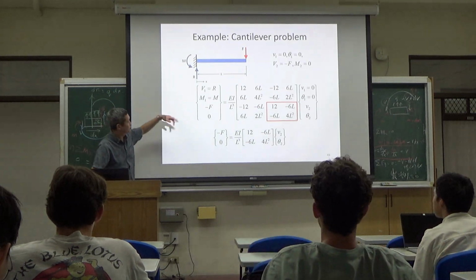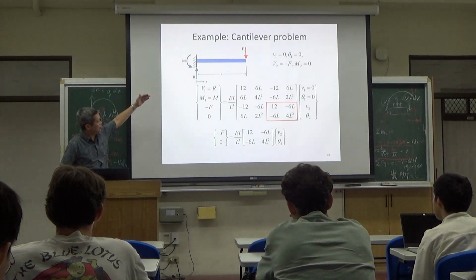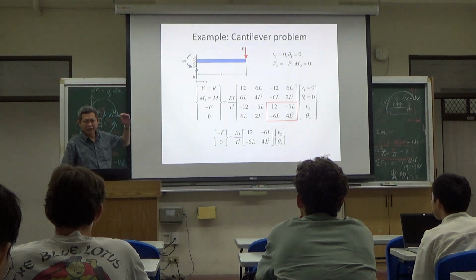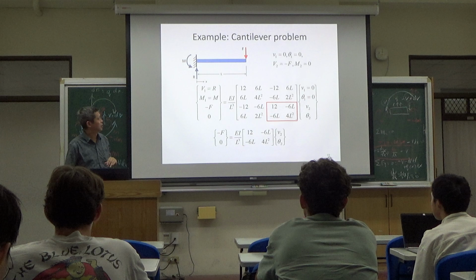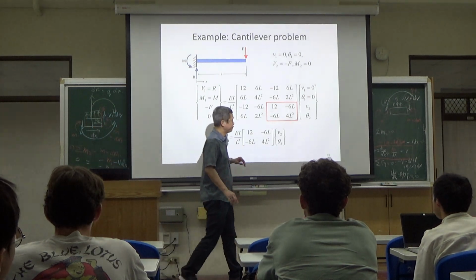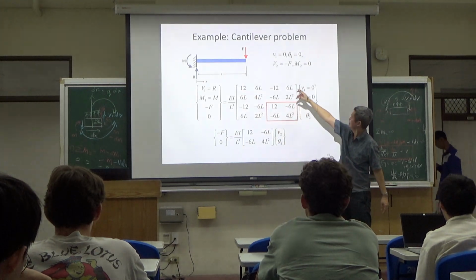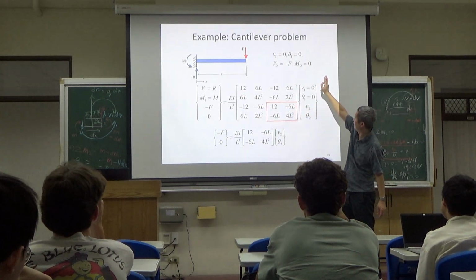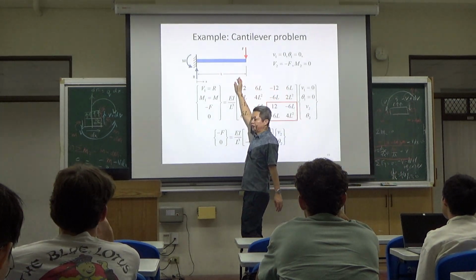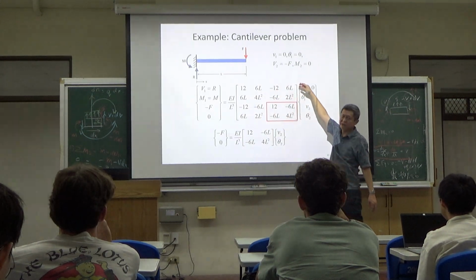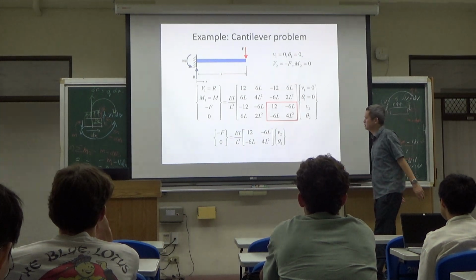But let's check what we learned. So the first thing we're going to do for validation is that the finite element formulation should reduce to a simple cantilever beam theory. What makes a simple cantilever beam? The left node, which is node 1, will have 0 vertical displacement and 0 angle of deflection. And then next, when you subject the right free tip to downward vertical force F and 0 moment, what will be the answer of finite element for v2?